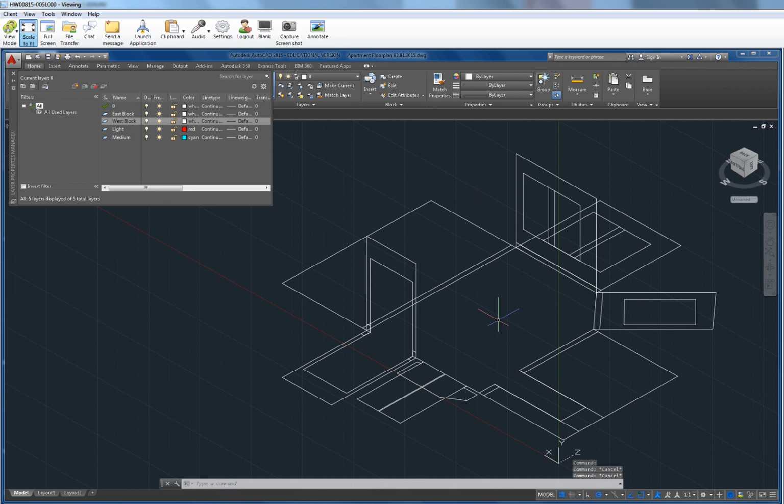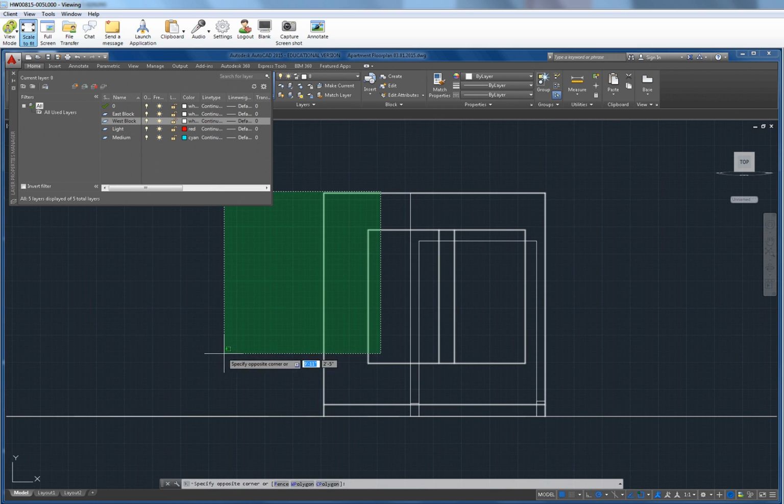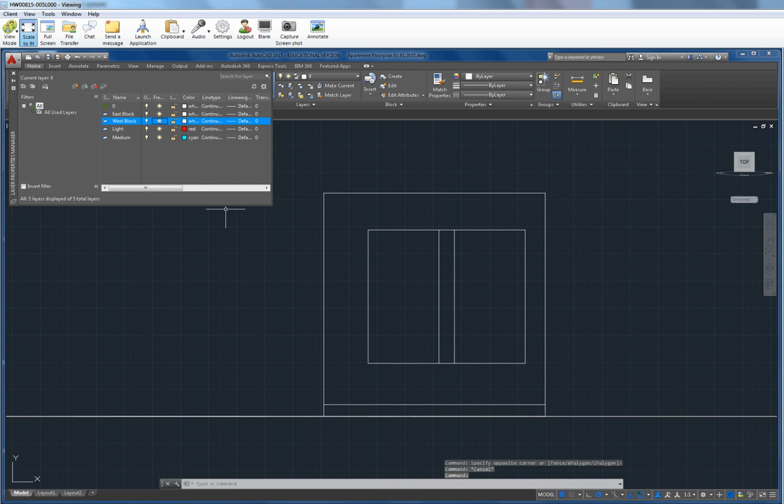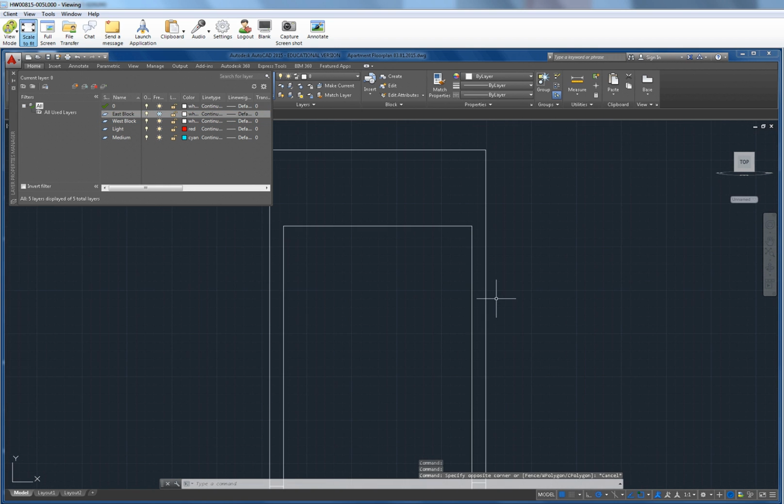And then that way, say I want to draw now on that opening. So I assume that's some type of corridor or something. That's hallway. Okay. So if I were to type in plan now, right? Plan, it's going to reorientate my drawing, in this case my drafting table, to the elevation. But I also see the east elevation, which could be confusing. Some people can just work that way. But if we turn the right one off, the east one, now we're just dealing with that elevation. So now if I start drawing on there, it makes a little bit more sense.